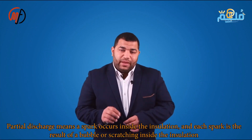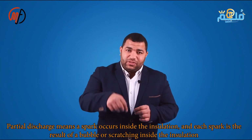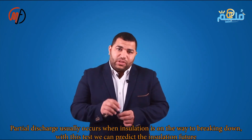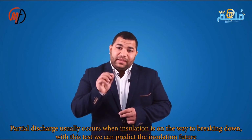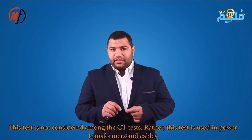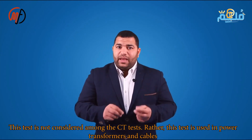Partial discharge, or PD, refers to the occurrence of small electrical sparks within the insulation. Each spark results from an air void or a defect in the insulation. Since partial discharge usually happens when the insulation is on the verge of failure, this test allows us to predict the future of the insulation. This test is not part of the site tests. Rather, the PD test is used in power transformers or cables.